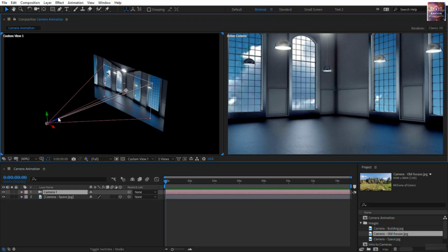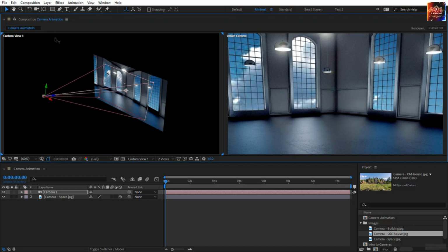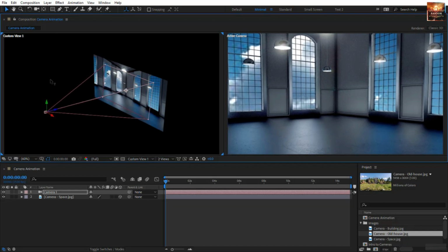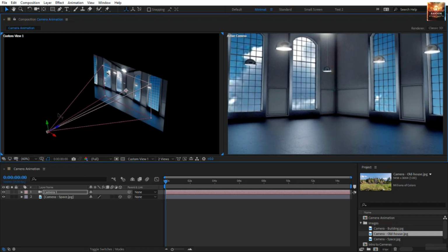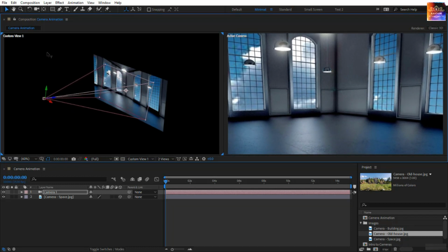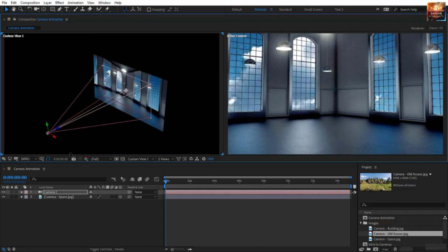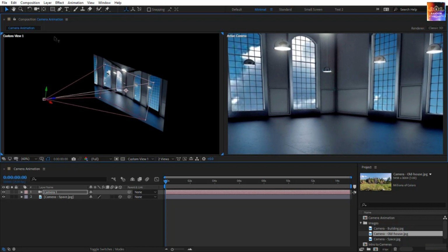Now there is another movement that you can do with the camera. If you point to an axis, for example, the Y-axis, and you press the Control key. If you are on the Mac, please press the Command key. Click on the axis and take it up. The point of interest is not moving, and hence you are not panning anymore. You are actually directing the camera by flipping it left and right or turning the camera in your hand.